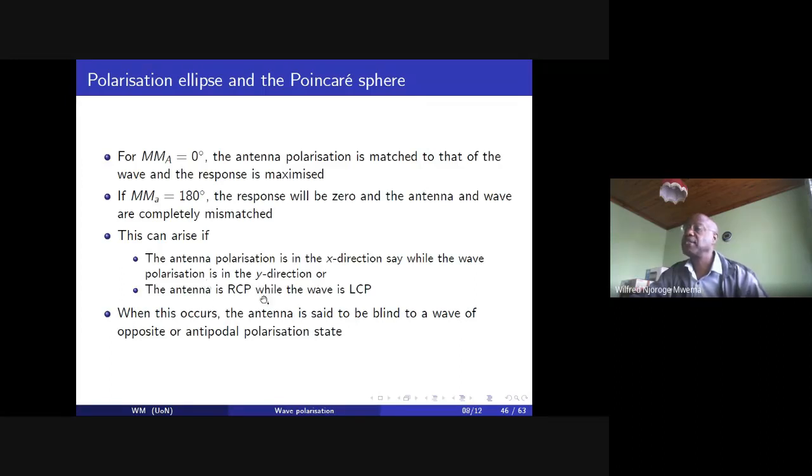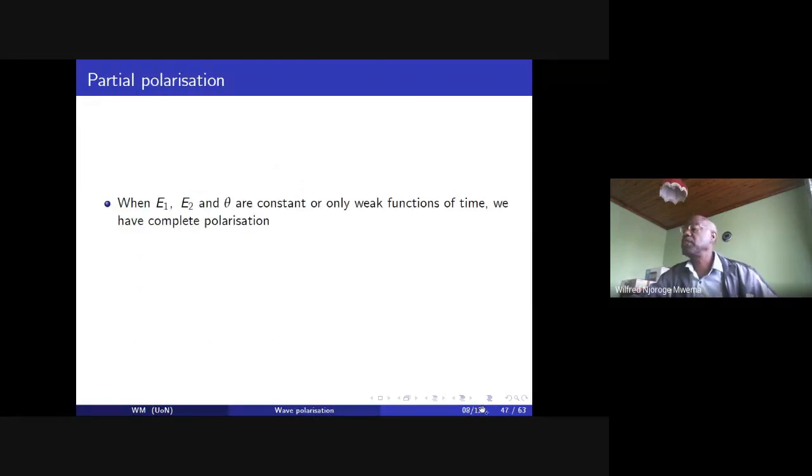If you are using a plane wave from the antenna on the satellite, then the polarization state on the ground will not be known. Therefore, it's usually much better to use a circularly polarized antenna on the ground, because then it will receive at least part of the signal coming through the ionosphere, so to speak. That rotation is usually referred to as Faraday rotation.